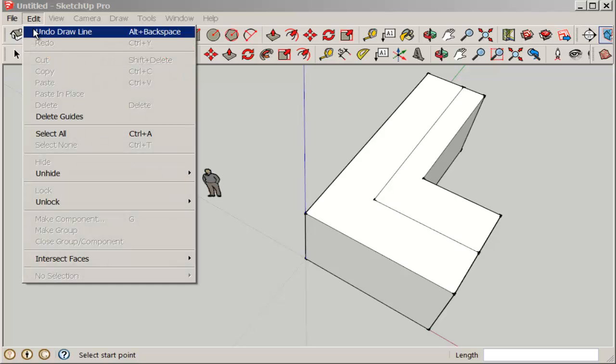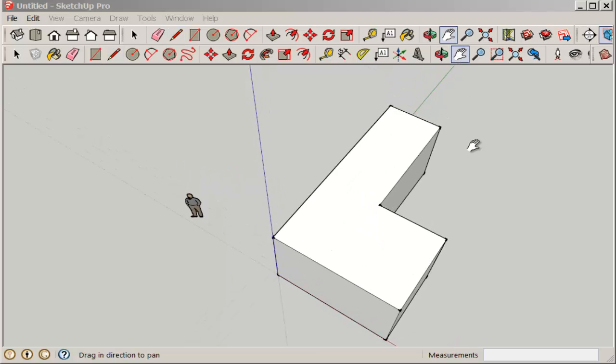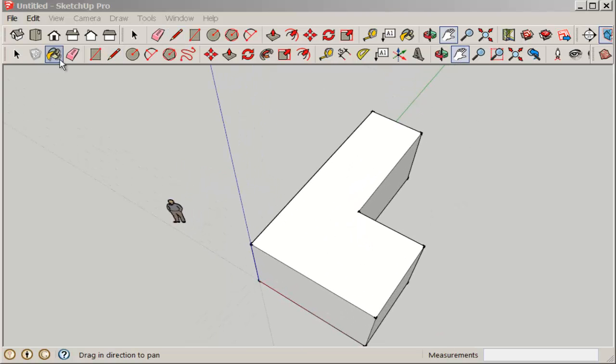So undo is always our friend, and we can undo all the way back to the beginning of the file. Let's try it again with the pencil at the midpoint inference. Hover over the other midpoint inference, slowly drag it back, and now it looks like that worked.